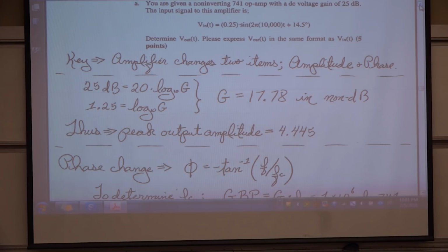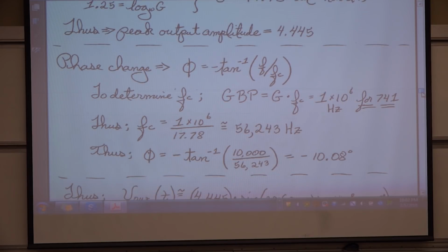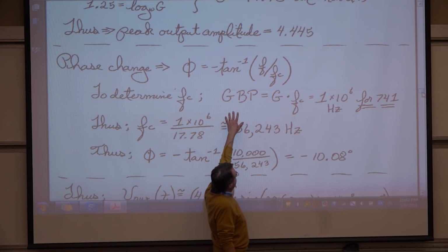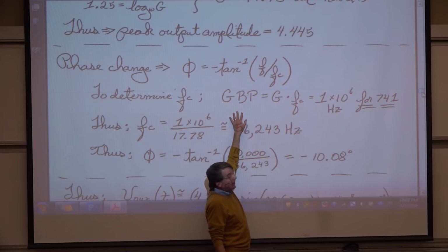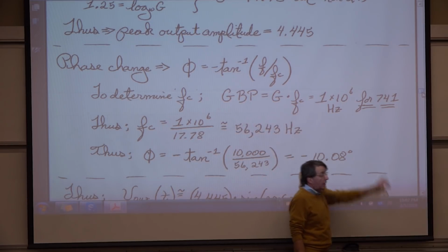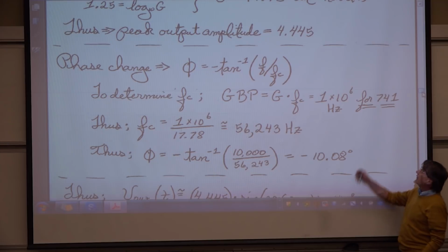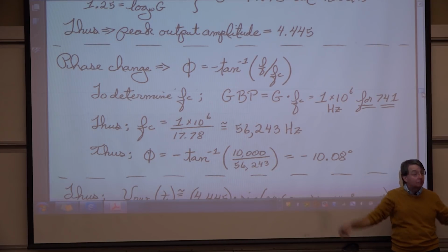All right, so I now say, I remember the gain bandwidth product. Now my colleagues, I don't think I have on the formula that the gain bandwidth product is a million. So just think of the op amp as a millionaire. The op amp is a millionaire, and it has a gain bandwidth product of 1 million. The gain bandwidth product, I love the name, it tells me what it is: the gain times the corner frequency. And for the 741 op amp, that's a million.